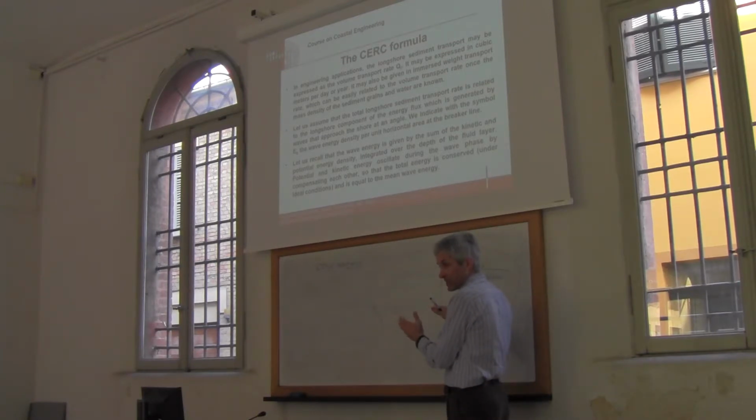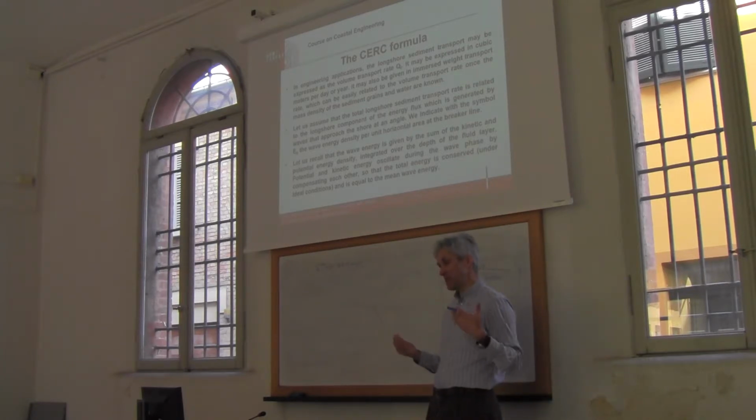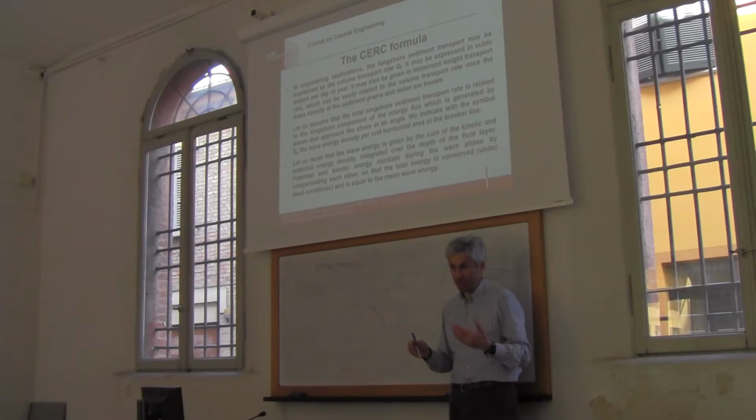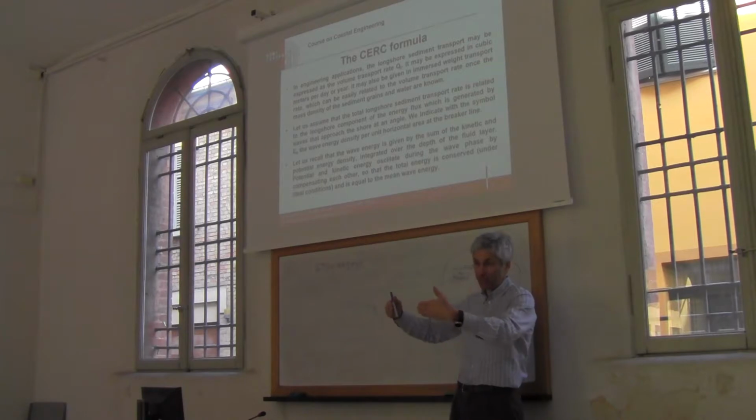And this energy flux, you know that it translates in a movement of mass. But given that it's difficult to relate the sediment transport to the movement of mass, we assume that the sediment transport is related to the energy that is transmitted by the wave. Why do we make this assumption? Why did they make this assumption? Because there is a clear relationship between the energy flux, the movement of mass, and the movement of sediments.